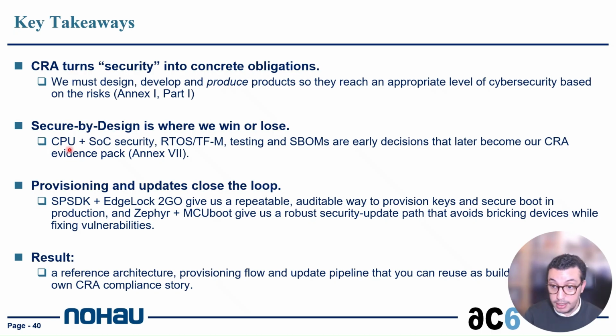So we decided to use some specific CPU and system-on-chip security. If you work on processor families, you can think about the V8-A architecture that has TrustZone for Cortex-A. You need to implement something in the secure monitor. You can use it in bare metal or by using Linux. You can implement OP-TEE. There are a lot of things that we can cover there. And of course, showing evidence of testing and how the SBOM is used. There is also the provisioning part. I used one from NXP because it gives exactly the answer I want on the CRA. You can find the same one on Renesas and on other vendors.